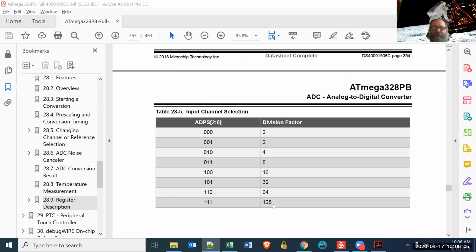If you can picture a counter that can count up or count down, and that's feeding into a D to A converter, a digital to analog converter. The output of that is being fed into a comparator with your unknown.